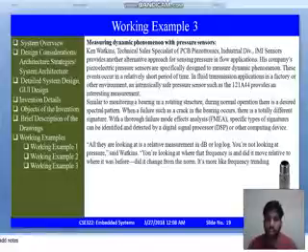environment. An intrinsically safe pressure sensor such as the 121A44 provides an interesting measurement, similar to monitoring a bearing in a rotating structure. During normal operation, there is a desired spectral pattern. When a failure such as a crack in the bearing occurs, there is a totally different signature. With a thorough failure mode and effects analysis, which is FMEA, specific types of signatures can be identified and detected by a signal processor, which is DSP, or other computing devices. All they are looking at is a relative measurement in dB or log by log.